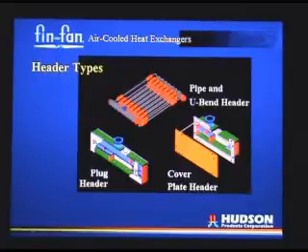These are more applicable to utility coolers where you have cooling water or another type of process fluid in here where you might want to take the cover off to clean the tubes. It's much more labor intensive if you have to pull the plugs on this unit. You have to unplug each one and then either hydrojet or rod out the tubes.